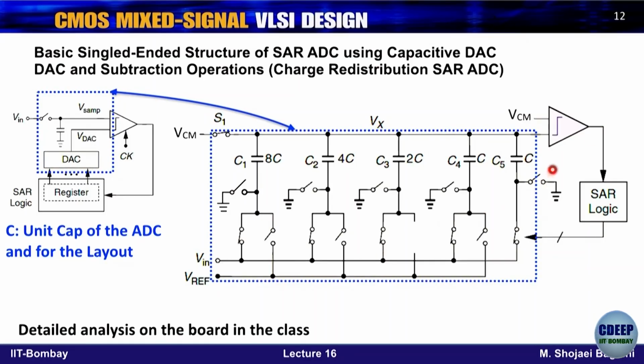Okay, and this is more often a clocked comparator, because the input of the comparator has to settle and then we have to activate the comparator. And then there is a common mode level, because in CMOS technology, we can't have 0 here. This is what you see in the difference. In Razavi's article, he has used a generic input of 0, but this is actually a common mode level, so VCM.